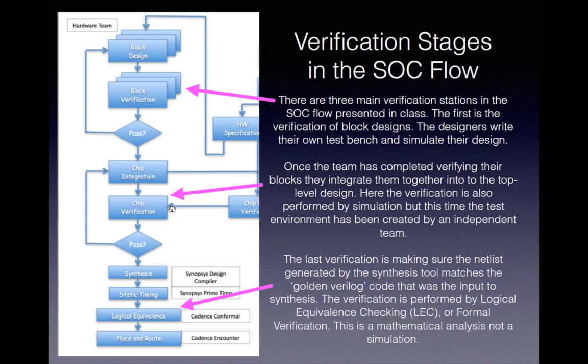And sometimes they require a little bit of hand holding, but once you get it, they're nice. They tell you that the synthesis tool has not changed the functionality. They tell you that the synthesis tool has generated the same logic that went into the golden Verilog. It's the static timing analysis that verifies the timing of the resultant netlist. The logical equivalence is the verification that the resultant netlist corresponds to the golden Verilog that was used to produce the netlist.